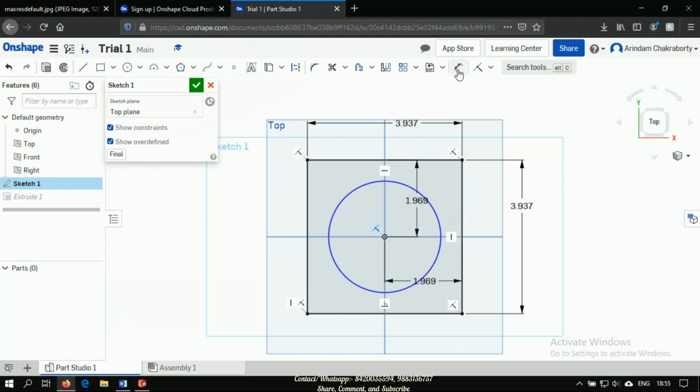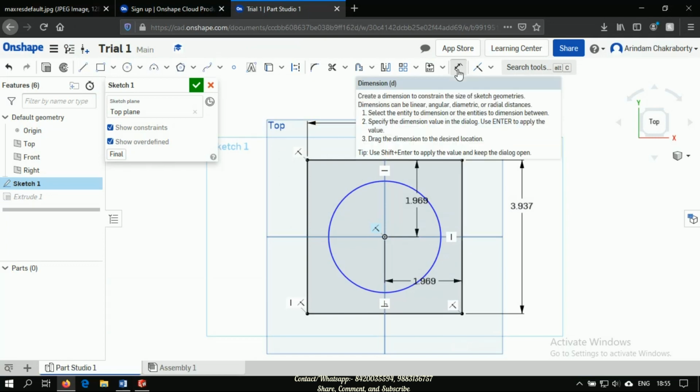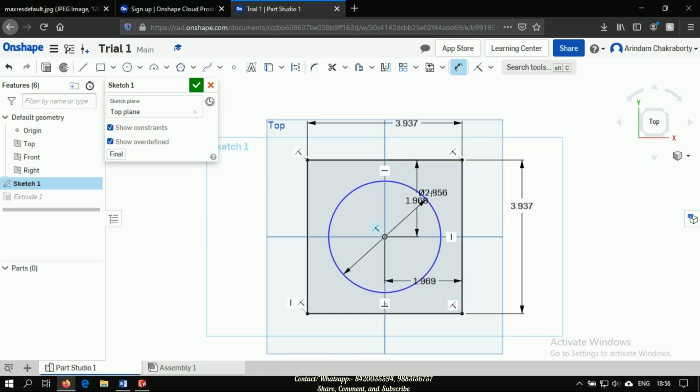So what I can do is click over here, this one. Okay, dimensions. Now you can see. If I bring it outside, you may ask me why I have done this, because it is very wrong to intersect any dimensions. If I bring this one through this one, that means I am intersecting this dimension. Okay, how much? 10 mm. Fine. First of all, you observe this one. What is this? This is the diameter. So 10 mm is my diameter.